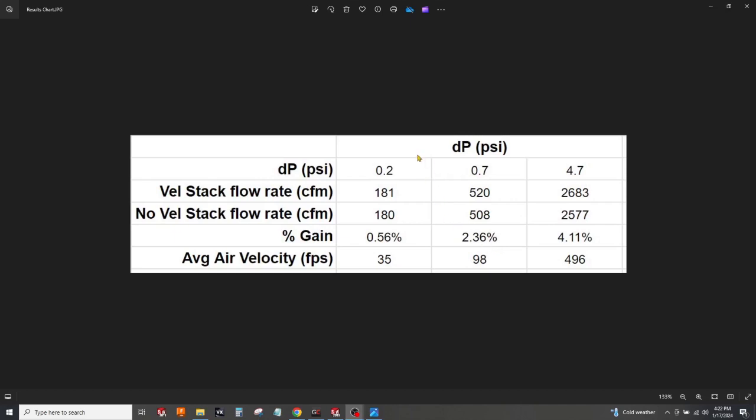And then when we go down to this much smaller pressure differential, well, we certainly still see a gain. Is it significant? Probably not, and certainly might be in the noise of the statistics of the CFD, but it's certainly not a loss. The other thing that is pretty noteworthy here is the average velocity. So this is the velocity of the air coming out at that same measurement location, and obviously this is kind of exponential, just like our pressure differential. So we would expect that.